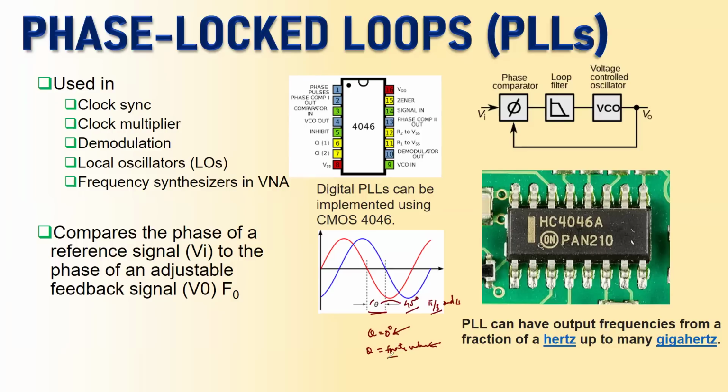And if the phase difference has a finite value, in this picture theta, it will remain so. So for a phase difference of 0, along with the red signal, the output or feedback signal will also have this kind of waveform. And in case you have a blue signal and you want to maintain this phase difference of theta, the PLL can also work in that fashion.